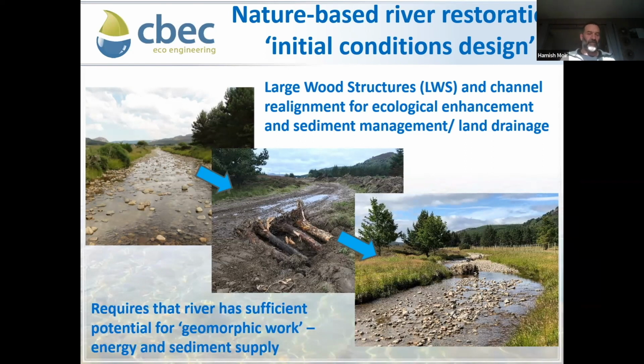We need to know the river has enough potential for geomorphic work in terms of the river's energy and the flow and sediment supply. So we do this by applying a sediment transfer model. So we built a very, very simple channel here, a very simple trapezoidal channel. But we knew when we applied the model that just a moderate flow event would rework the sediment and produce this type of